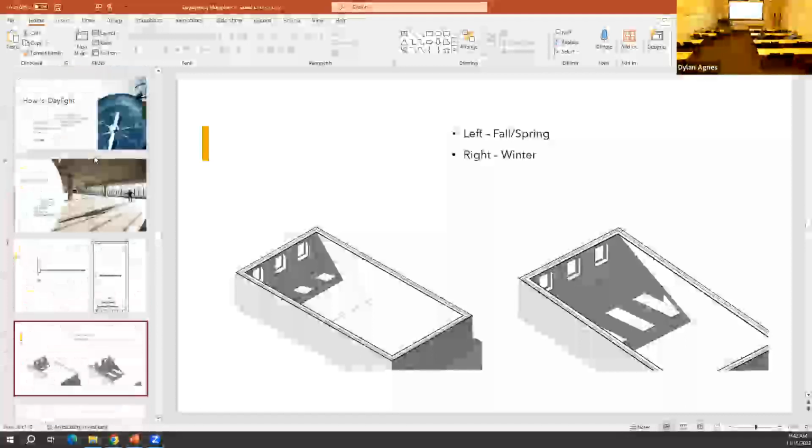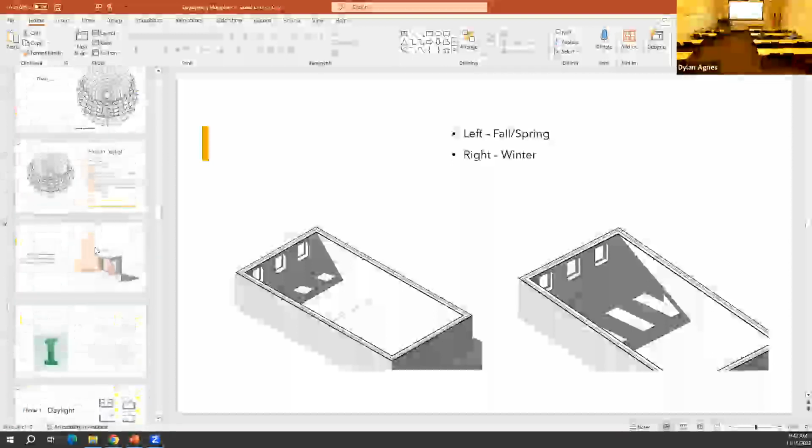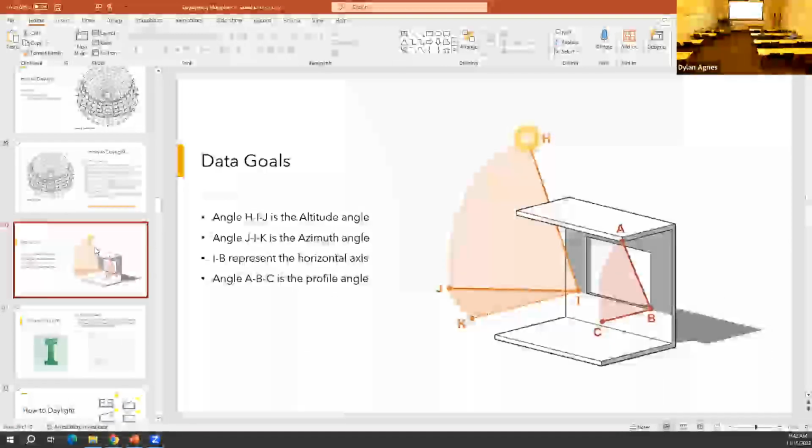Do you have to know your orientation geometry? Okay. So knowing the altitude, the azimuth, but Revit is pretty nice in that it can do that for you if you want. Me, I get a little more technical because people want to know exactly the square footage or the area, and I compare that against IECC and do a calculation on here's how many kilowatt hours are used for the lighting system. Here's how many kilowatt hours we can reduce based off of daylight availability.